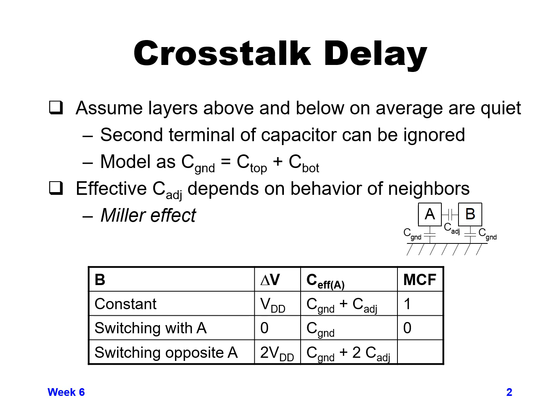So this gets seen as an effective capacitance of 2 times C adjacent. For our effective capacitance calculation, we have to multiply C adjacent by a factor of 2, which is the Miller coupling factor, and this will cause the signal to be a lot slower, switching in opposite directions to neighboring signals.